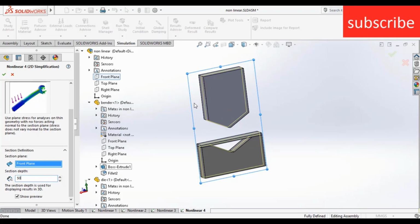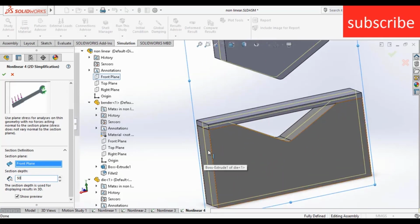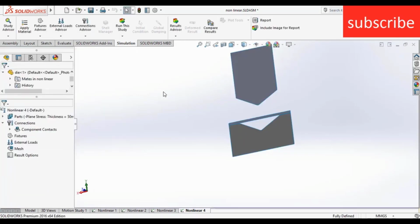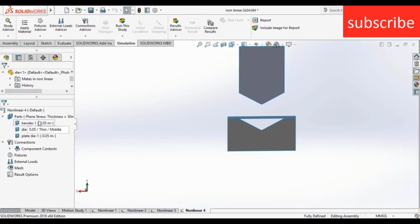So make sure you enter the value of width the same as the assembly or the components. So here I am typing 50 mm because my extrude is 50 mm. Click OK. After that you can see my 2D geometry. Now what we need to do is apply material. Press Ctrl, click on bender and die.